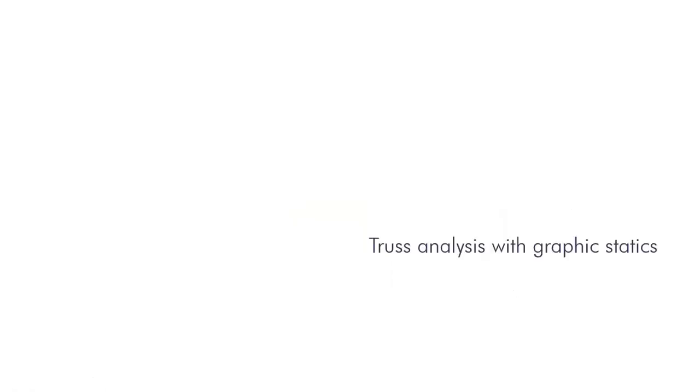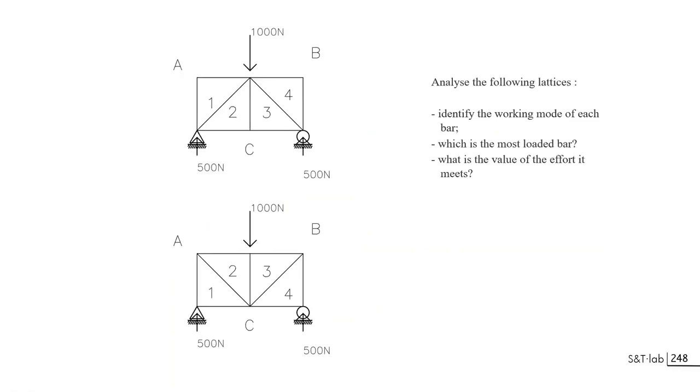Let's move on to the truss analysis, and then we'll be ready to go to more complex topics and applications in terms of design. If you have very simple trusses, you can see that there are singularities, things that are quite special about this. You know that these are hinge systems, so if you are pushing here, you are crossing a perpendicular bar, so you cannot transmit a force through this bar to here below.